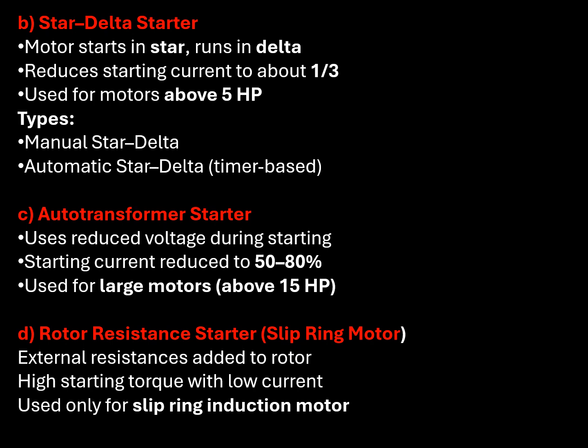Next category is star delta starter. Motor starts in star, runs in delta, reduces starting current to about one third. Used for motors above 5 HP.